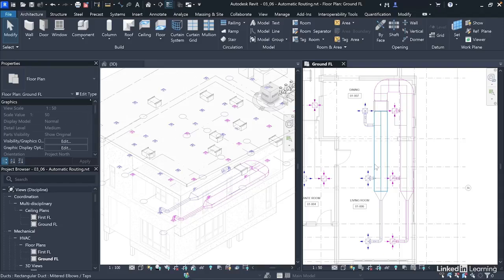Now, another limitation is that the conversion settings that we opened earlier only allow you to specify the duct types and the offsets. So that means Revit automatically sizes the ducts for you using what is available in the mechanical settings and based on what it believes is best. So it doesn't give you the room to size it. But as an experienced engineer, it might be more convenient for you to size the ducts as you manually connect the system components. So we'll still look at duct sizing in the next chapter. Our focus there is modeling.